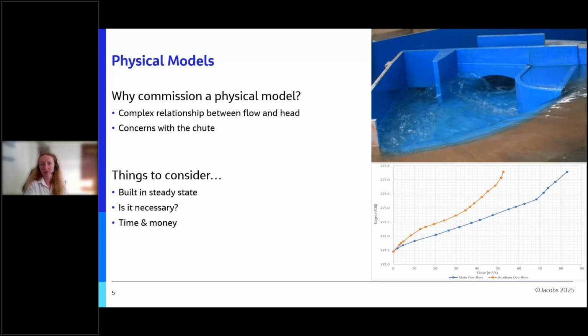safety requirements. The price of a physical model can vary a lot depending on its size, complexity, and the company who are building it, starting from a few £1,000s in my experience. The main concern, however, is often time. If you consider the whole life cycle of a physical modelling job from scoping, commissioning, build, witness test and reporting, it may not be an option if you've only got a few months until your reg date.